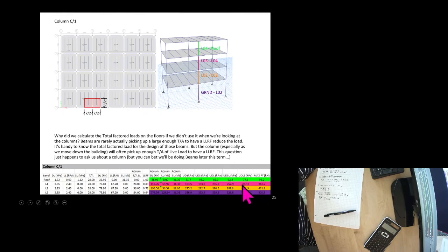So it seems to be the same for the rest of the way going down this column. In your assignment, you have one that is more complicated. You have one that incorporates live load reduction factor, but also incorporates having some wind cases and some seismic cases. And the goal I'm trying to prove here is that you can have different load combinations govern a column at different stories because it has different loads or values of loads acting on it.